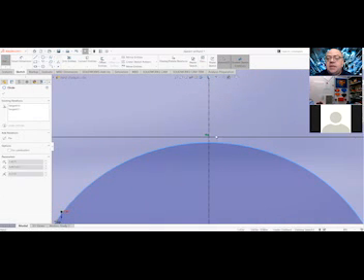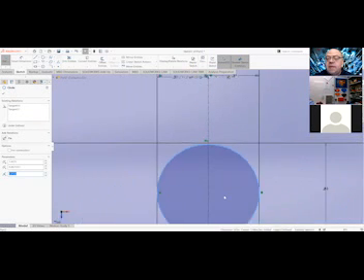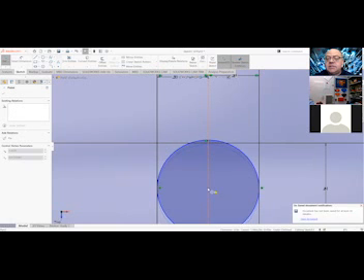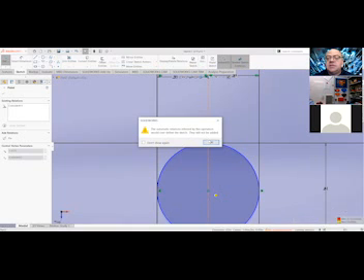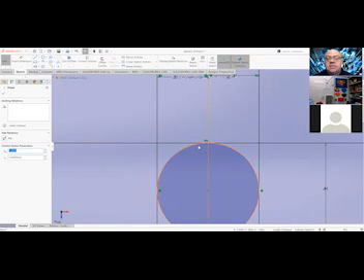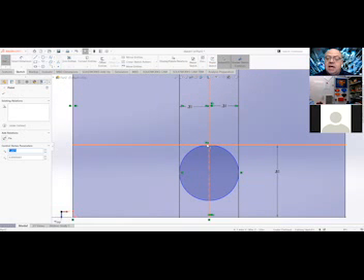Well, I grab and drag, turn that circle off, select the circle, and drag it back up, nice and easy, so they touch. And now it says it's overdefined, okay? So now once I get the message back again, I've fixed that connection. So now they're connected. You have to be a little patient with it, but that's what happens if you do it with the 3-point circle, the perimeter circle.